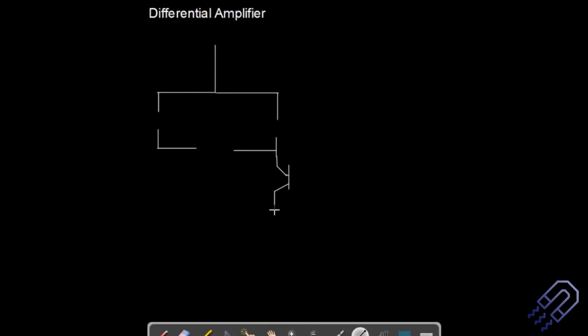This is basically, you can say, an integrated circuit. So if I'm drawing a transistor, it means that we won't be able to look into it externally when we actually take up a differential amplifier, but it's there internally, and we have the differential amplifier there. So see, I have drawn two transistors, and those two transistors will act as the input terminals. We have the input either from this end or from this end, based on which we can call them an inverting or a non-inverting terminal.